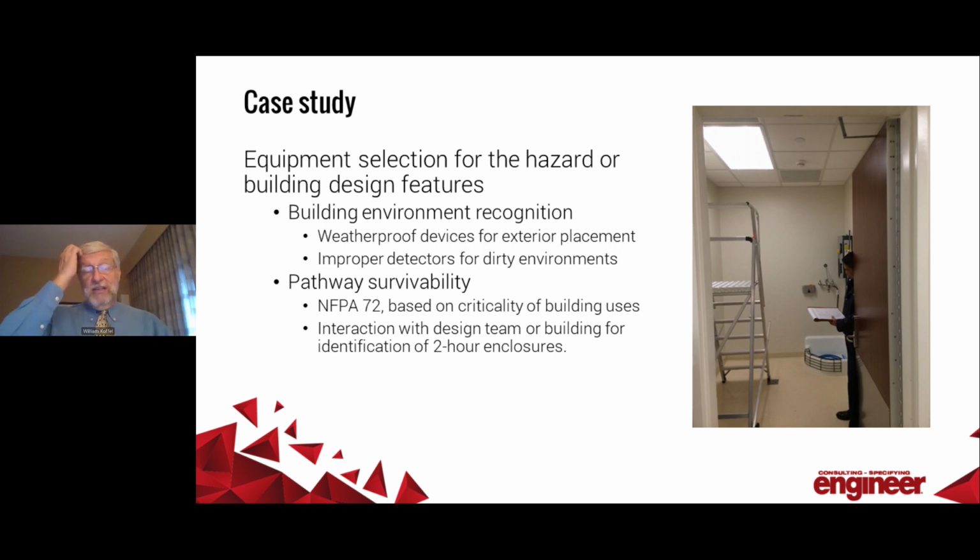So this is an environmental services closet in a healthcare facility, again, not in the US. You can see that there is a detector towards the back of the room right above where they go in and they fill buckets with hot water. The hot water there is a little hotter than it is here in the US. The door is typically closed. They generate steam, and they were getting nuisance alarms.